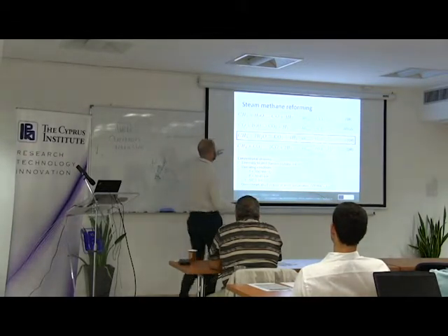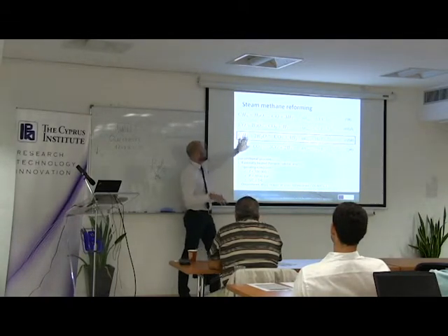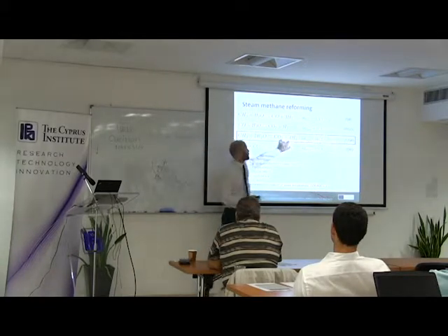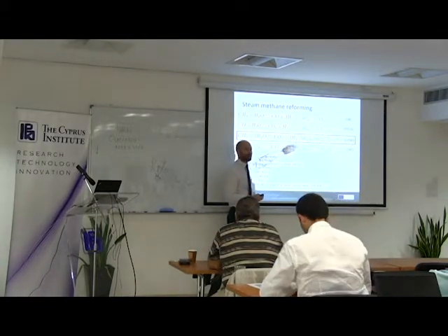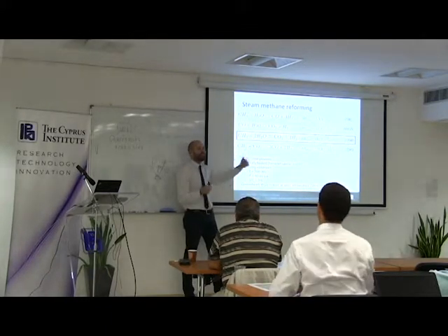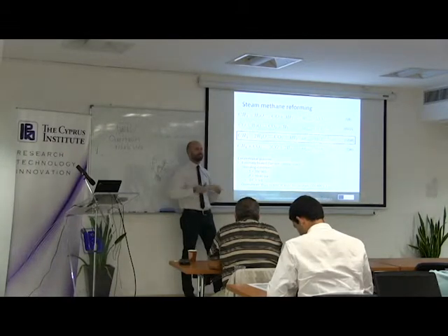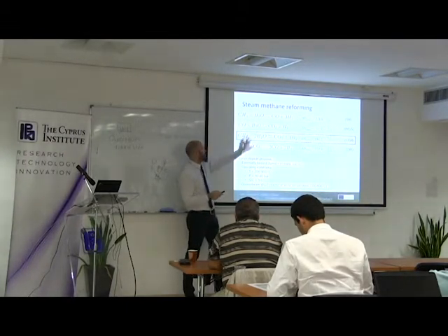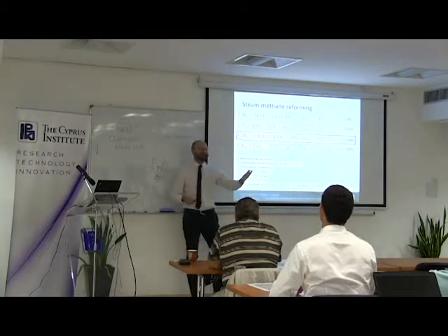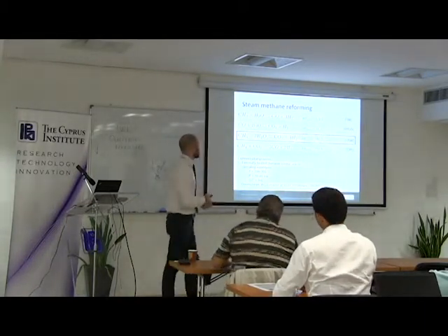Otherwise, it is an equilibrium reaction, which means that if the temperature is too low, when these two components that are fed to the reactor start to react and form the products, the products will start to react back and form the reactants. Then you will have a very low yield. Even if you have a huge reactor, whatever effort you make, you will convert like 10%, 15% of the methane you're feeding. So your process is not convenient.